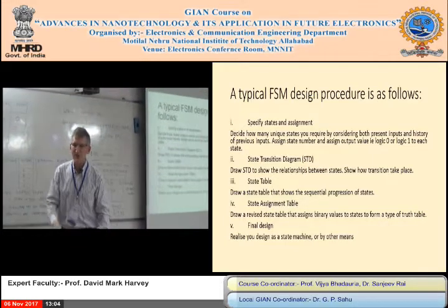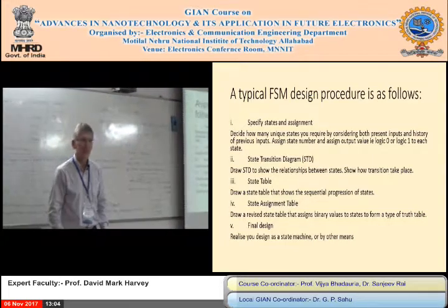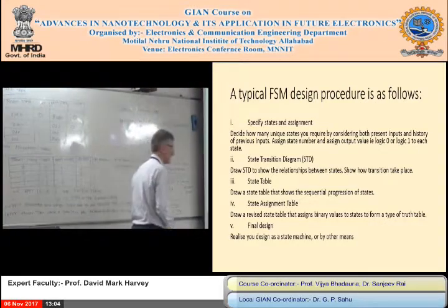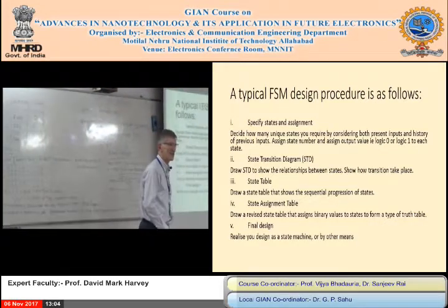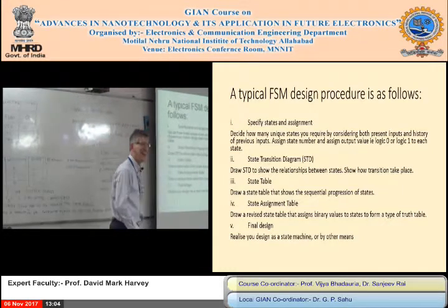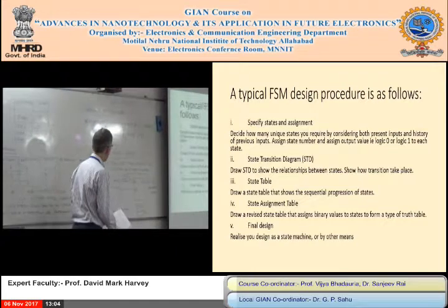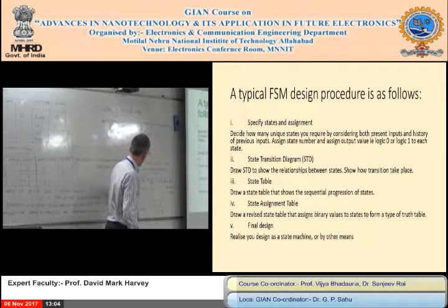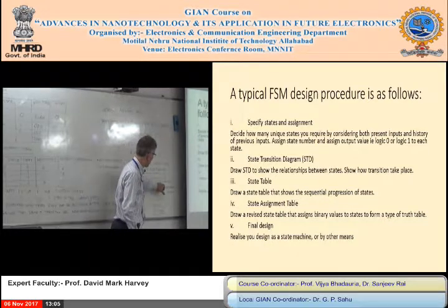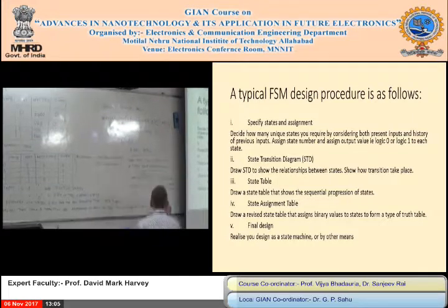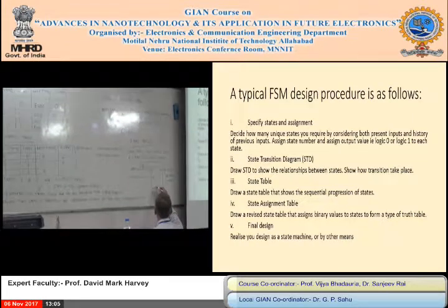There's one thing missing. Can you spot it? Reset. That's right. I left it off deliberately just to see how desperate you are to get your lunch. So, as I said, textbook design is like that. Simple. Input, exclusive OR gate, clock, odd parity output there, but we haven't set it up to a state. So we need to initialize.